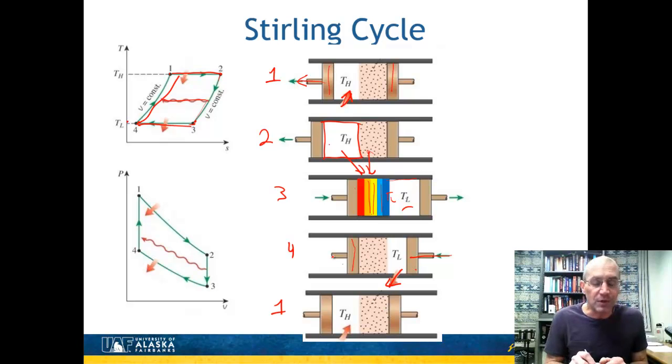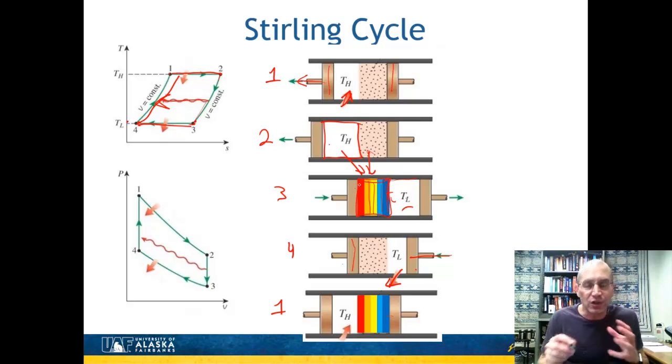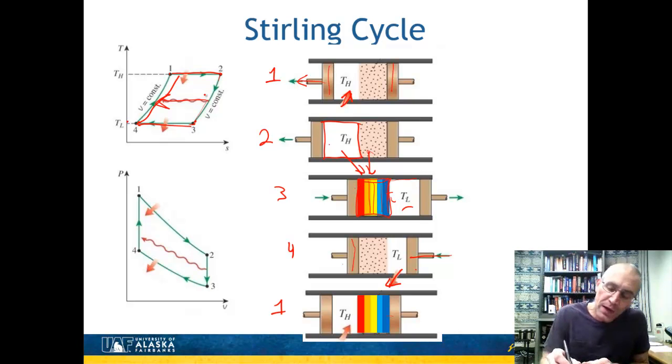Again, I move the material across, pushing it here. Remember, here's the regenerator, and the left-hand side is warm, the right-hand side is cold. As this fluid moves through this porous material, it's going to heat back up to TH. And so there's that regeneration step on the receiving side. That's the way the Stirling cycle works, and this regenerator is a key component that just stores this energy temporarily. It stores it as it comes out over there, and then it's received over on the left-hand side.